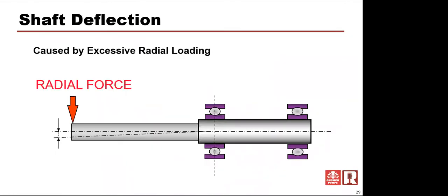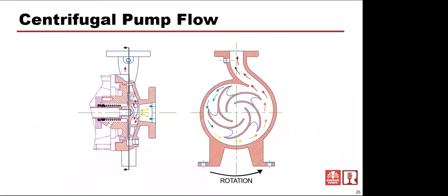There's a lot going on inside this casing, and when you create that back pressure, and we're going to talk about cavitation, when you create all of that backflow, can you imagine how much turbulence you're causing inside this casing? This casing, a 3x4-8 that we were talking about, at 435 gallons per minute at, let's say, 8.3 pounds per gallon, is 2,400 pounds of fluid moving through this casing per minute.